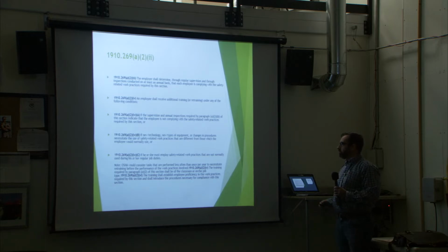If the supervision and annual inspections required by paragraph A2 III of this section indicate that the employee is not complying with the safety-related work practices required by this section, or if new technology, new types of equipment, or changes in procedures necessitate the use of safety-related work practices that are different from those which the employee would normally use, or if he or she must employ safety-related work practices that are not normally used during his or her regular job duties. So OSHA could consider tasks that are performed less often than once per year to necessitate retraining before the performance of the work